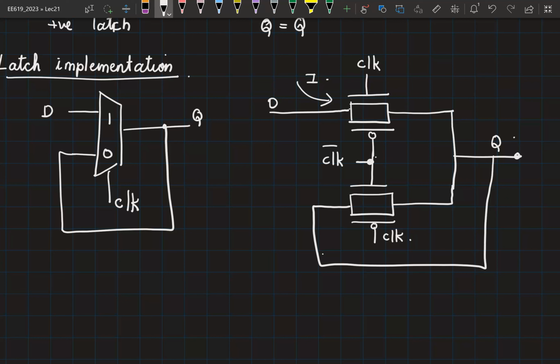Right? So the problem with implementing your latch just like this is, of course, you can implement it like this, and then depending on where you use it, you can characterize it, right? But generally, when you design a latch, it is going to be used in multiple places. So if you include the drive strength information also with your design, then it is more usable, right? It just becomes a matter of plug and play. Wherever you want it, you take the full circuit, plug it. It has already been completely characterized with the drive strength that is included with it, right?